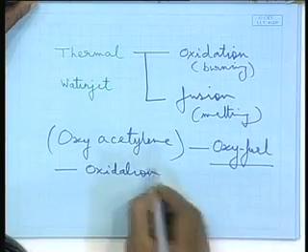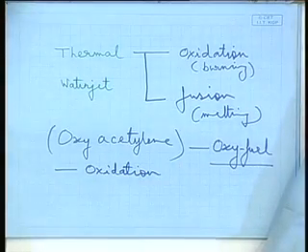That means, what happens in the process? Metal is converted to oxide, right, and thereby the molten oxide is thrown off. That is how you achieve a cut edge. So, you will find that in the process, first you have to heat up the plate and then you put in excess oxygen, extra oxygen. If you recall, if you have cut in the first year workshop practice, you heat the plate with the oxyacetylene flame from where you want to cut. After a few seconds, you press another lever in the cutting torch, and you may have observed the sound changes, meaning more oxygen by pressing another lever.